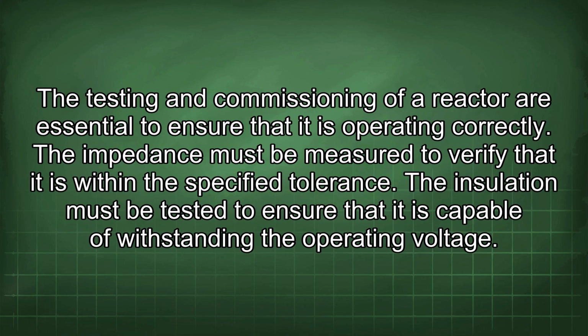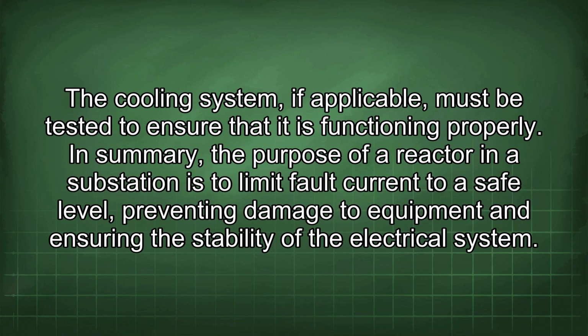The testing and commissioning of a reactor are essential to ensure that it is operating correctly. The impedance must be measured to verify that it is within the specified tolerance. The insulation must be tested to ensure that it is capable of withstanding the operating voltage. The cooling system, if applicable, must be tested to ensure that it is functioning properly.